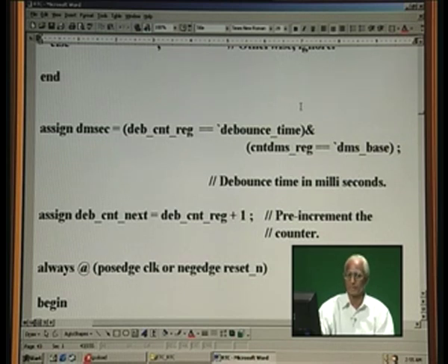29 is actually to be read as 30 because 30 clocks are involved, although you set 29. It is because we start counting right from 0, 1, 2, 3, up to 29, all inclusive, which is 30 actually. So 30 into 0.1 millisecond would give you 3 millisecond. That is how you get a 3 millisecond debounce time. That means whenever a switch is pressed, it will make and break for some time, say 2 to 2.5 millisecond, based on real time experience.